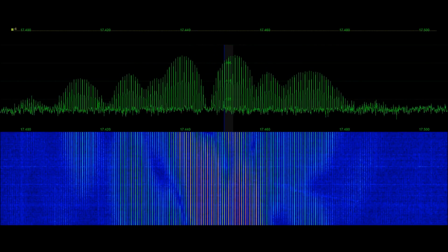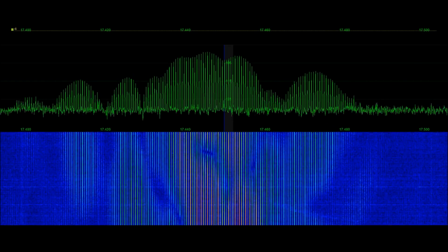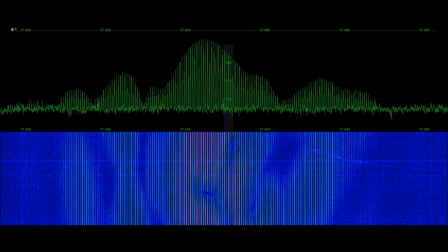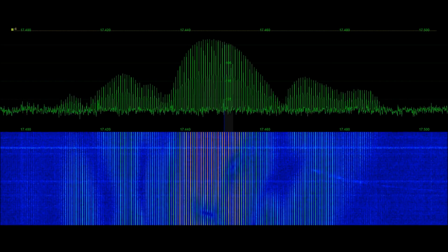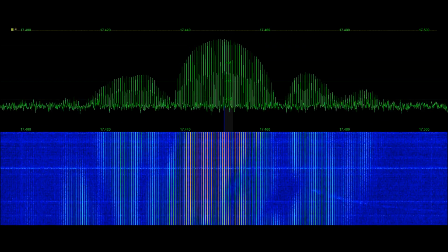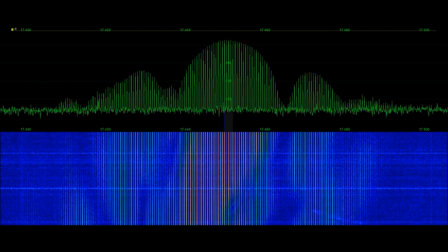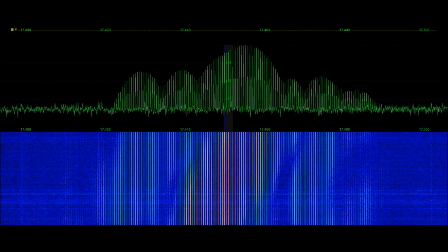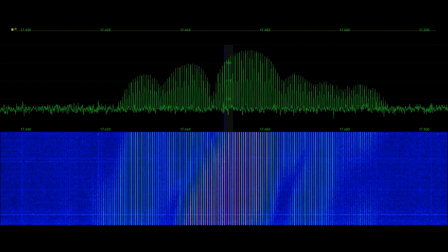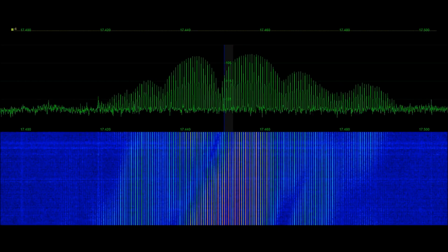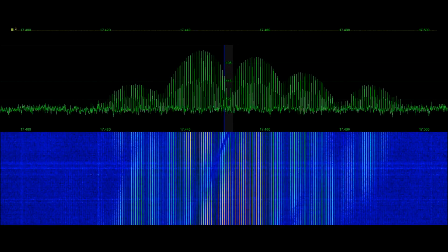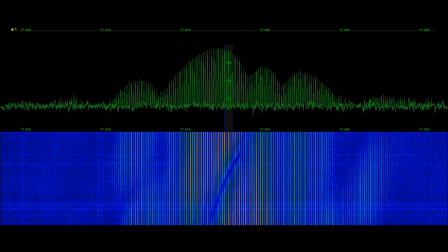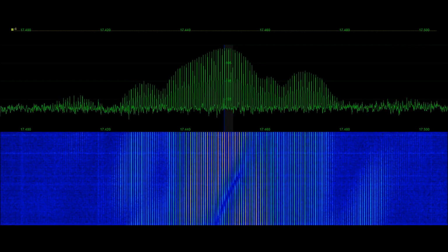Now there's a lot of selective fading in the signal, but we'll start to identify certain parts of the signal and analyze them going forward. But first, a little on how this signal actually differs from some other radar signatures that we've taken in the past. Specifically, over-the-horizon radars operating in a different modulation format, specifically FMCW, or frequency modulated carrier waves, or FMOP, or frequency modulated on pulse type radar signatures.